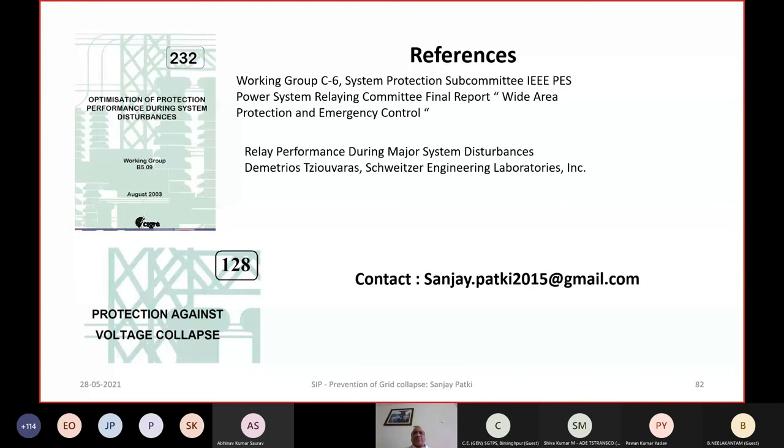So that is the sort of compromise you will have. So it is a good idea to keep revising the stabilizing resistor value periodically as the fault level changes, and go by the actual calculations of the voltage developed for a through fault condition. That is actually the better practice.